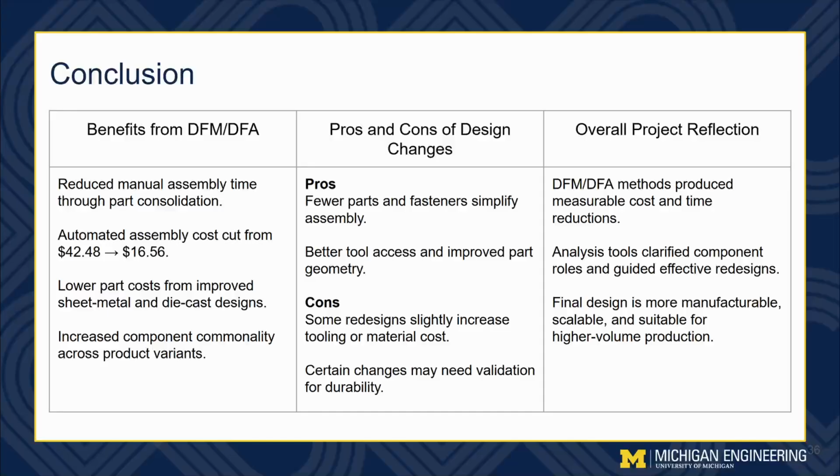And to round out this presentation, we have our benefits from DFM/DFMA, which are the reduced manual assembly time through part consolidation. We saw the lowered costs in automated assembly and improved costs from changing the designs of the parts. These design changes simplified assembly and created better part geometries, although there are studies that could be done to validate the durability of these changes.